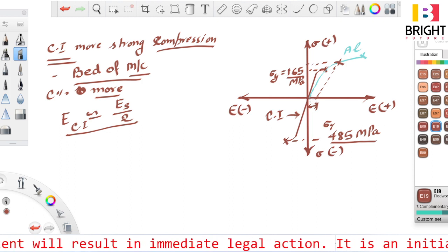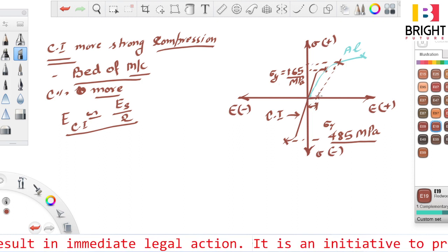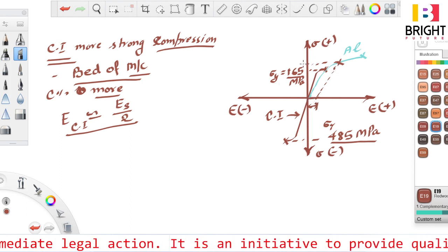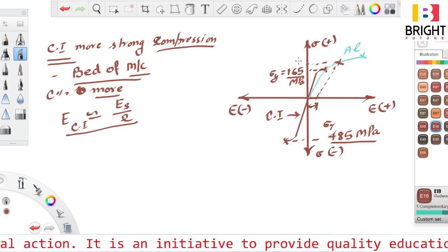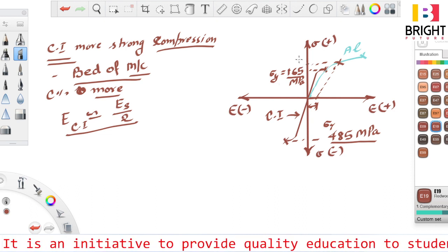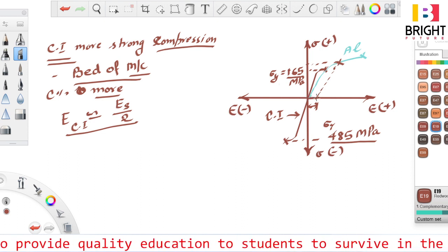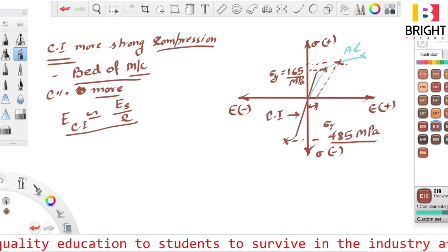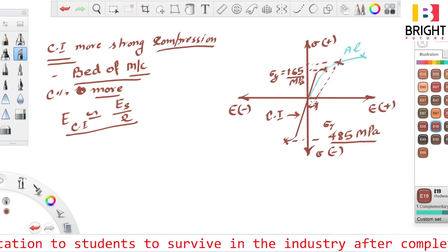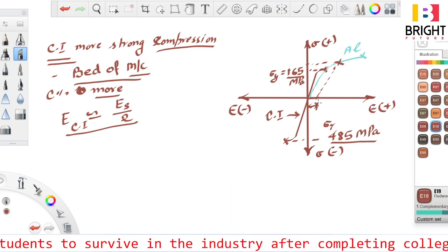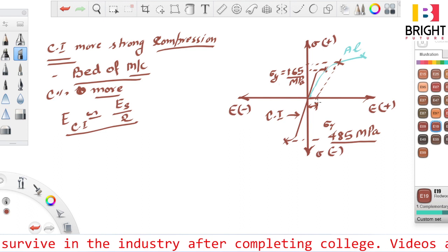We say that at this much fracture strain aluminium will fail. We will not say that at this particular stress it will fail, because that point is not clear on the stress strain diagram. This method is known as the offset method, which is used to find the yield point of aluminium.